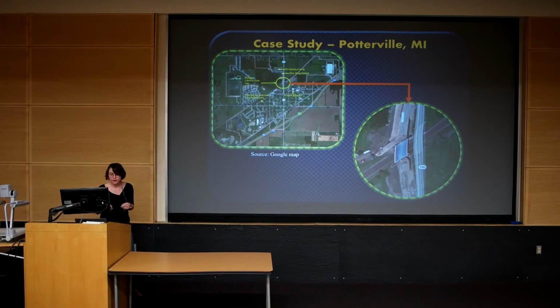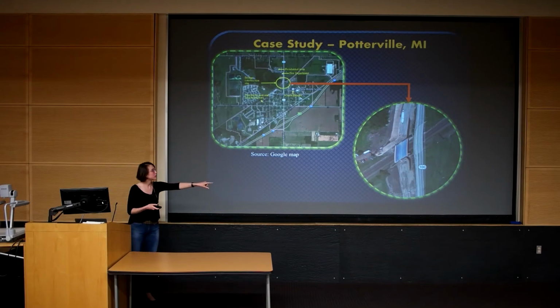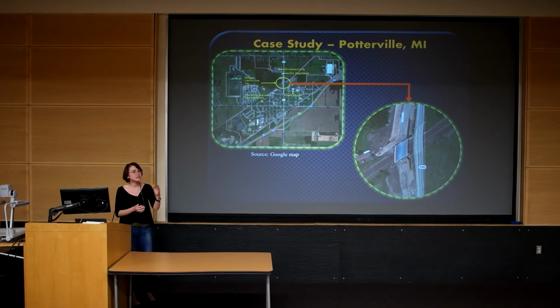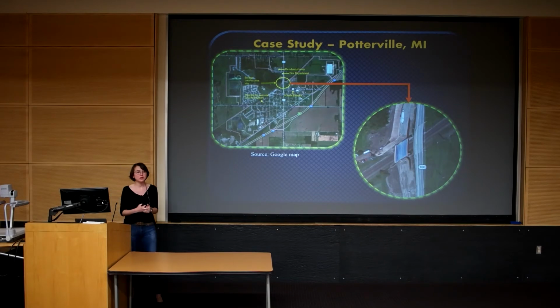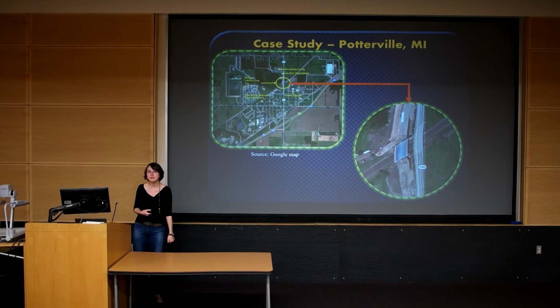So here is the actual construction timeline. They construct a new bridge near the existing bridge, so they keep the traffic flowing. And then for 2 days, they closed the road link, demolished the existing bridge, and slid the new bridge into its permanent place. So that is why the mobility impact time here is 2 days of a weekend, and the reduced speed limit duration is 237 days for slide-in bridge construction.